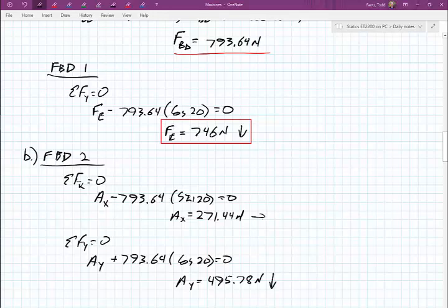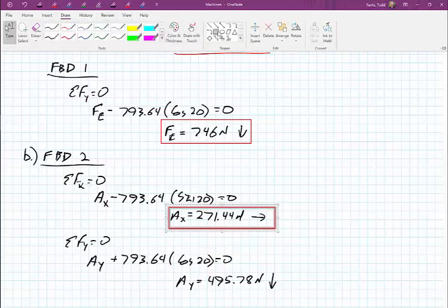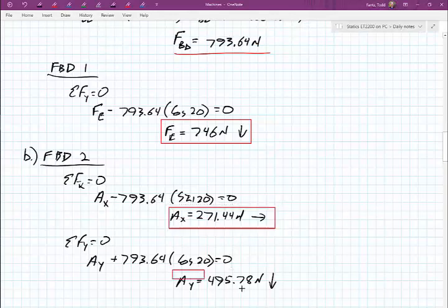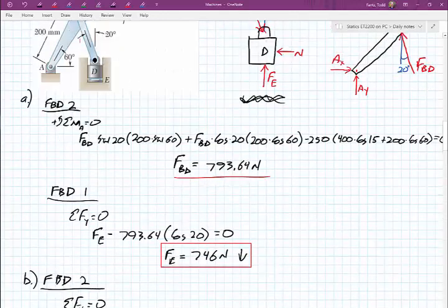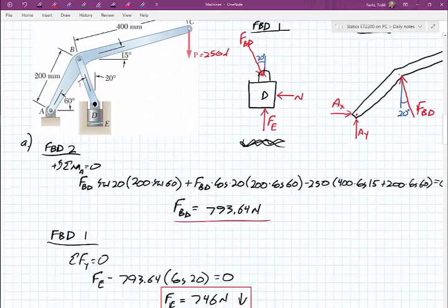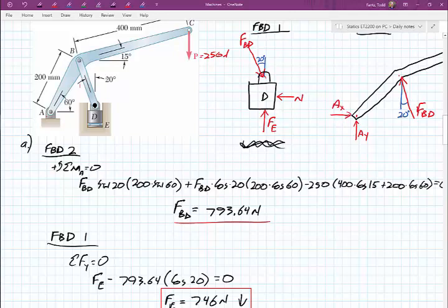This one was positive. I could combine that into a single force. I do that in the notes if you want to see that. It's just that using Pythagorean theorem. One last little step, not really overall important, unless you were designing the shearing stress on that pin, and then you would be looking at an overall force. So hopefully that problem was a little helpful in explaining how you're going to break these things apart.